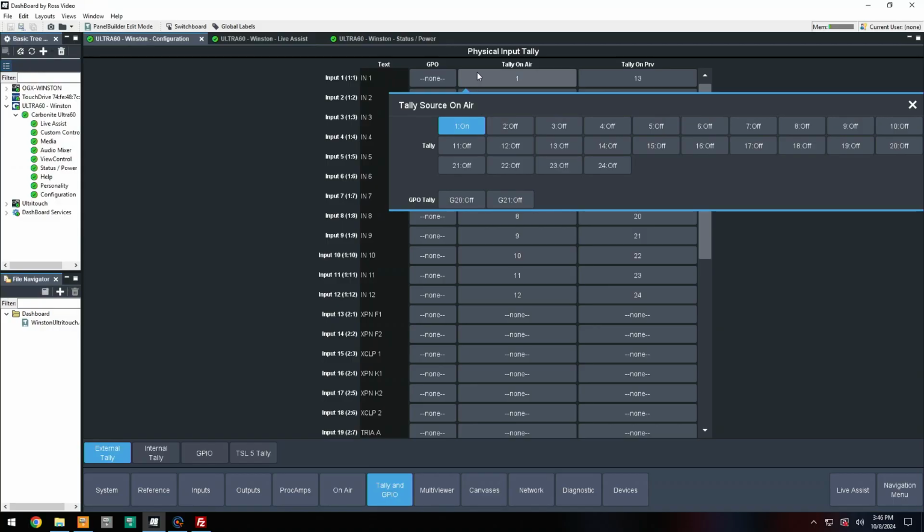The other thing is when you're assigning Tally connectors, these physical connectors, when you look on the back of the frame, there's one DB25. It's covered in the configuration guide, but there's one DB25 which has the 24 Tallies and the common on it. Tallies are contact closures. So these are open collector transistors. They aren't going to pass high amounts of amperage, but they're perfect for things like CCUs where you wire them in. It's providing the amperage that passes through and closes its switch, or it's going to provide it to put on the physical Tally lamp.